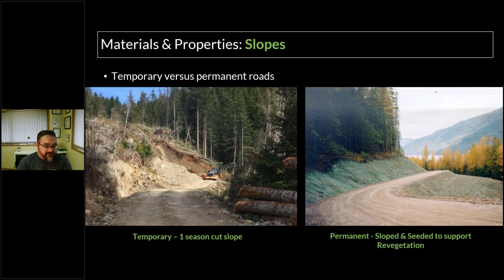So in the same example of till, you can cut that very steeply and it will ravel over time, but you're not disturbing a lot of ground, so you're end hauling less, and you'll have less cut slope or less disturbed area that's now going to be subject to mechanical erosion or rainfall, or intercept more area of groundwater. So those are things that you need to understand about material, and then understand about how that impacts your road and the life of your road.